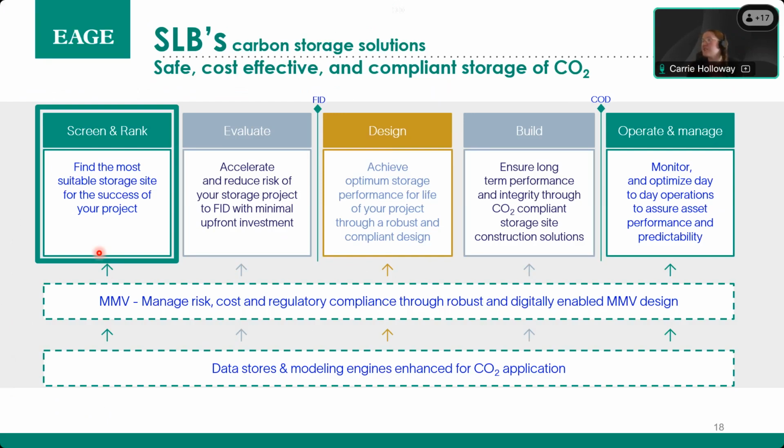In terms of the injection pressures, we do full geomechanical studies to understand the critical pressure to which we can raise the reservoir, in terms of at what point we may fracture our seal. This is especially important if we're looking at carbonates. These are more easily fractured.